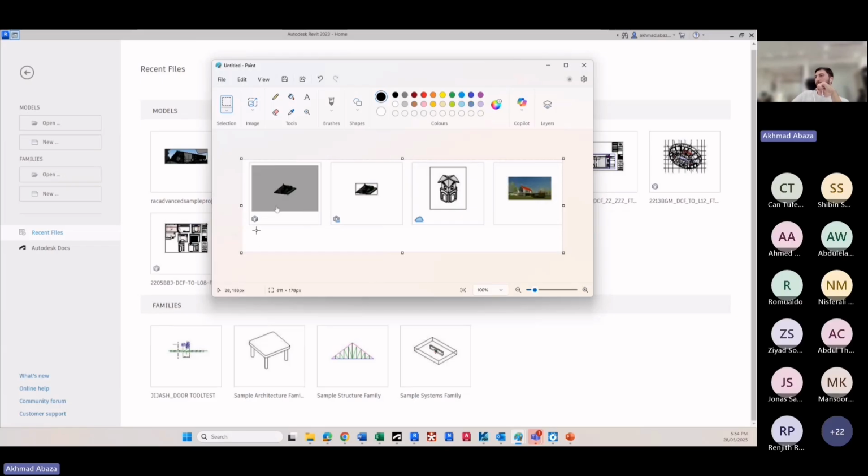The first one, as we said, is the central model, and it's like putting a file on the server and everyone can access this file. The most important thing is that we should create a new local from this central model, since we will not work on the central model directly.